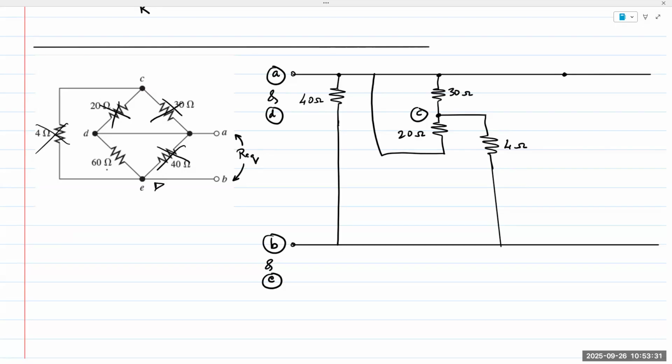D is right here at A. So that's 60 ohms, also done. Then I can check and verify for myself. I counted 5 resistors in the original circuit, and I've redrawn the circuit, and I still have my 5 resistors, meaning all resistors are accounted for.